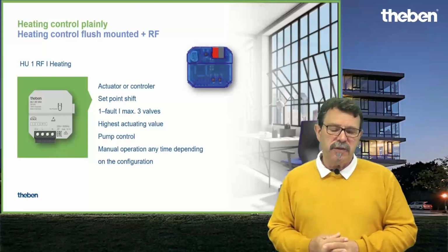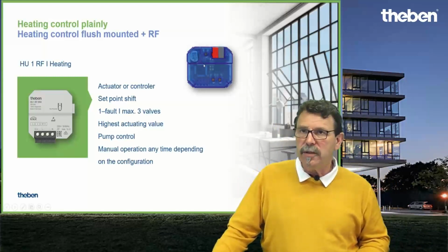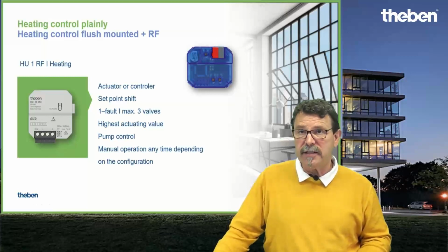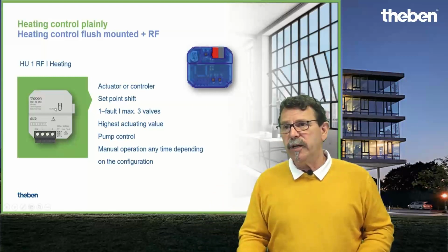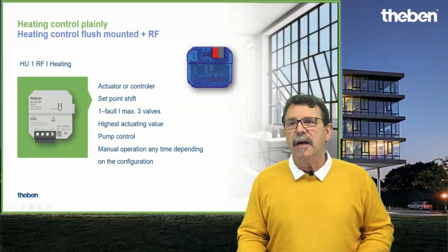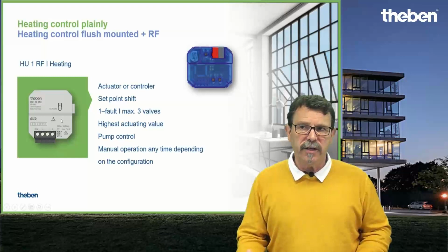And what you can do in such a project is, for instance, use a media coupler, which talks RF secure. This has to be linked, hardwired, to the KNX bus system, sure. Then we need the RF actuator, where we have to apply 230 volt to give it the reasonable power. And then via RF, you send the heating values through the media coupler to the heating actuator.